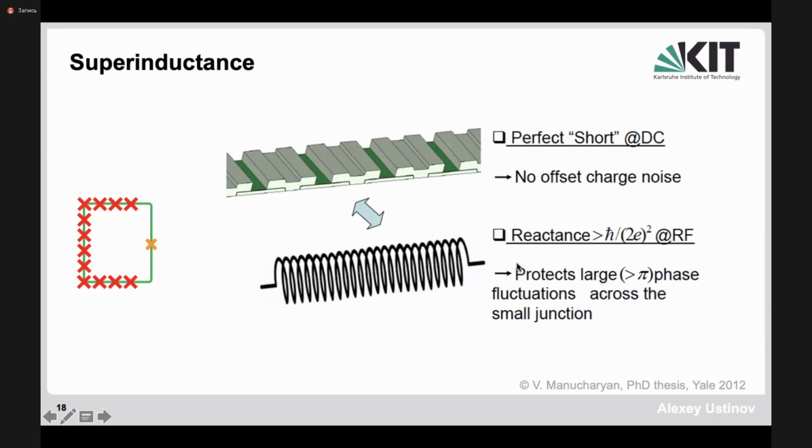As I said, the reason for using this inductance initially was thought to be the trick to avoid the low frequency charge noise due to the random charges which are moving on the substrate and fluctuating there at any temperature. They are present there due to contamination of the surface, due to charge traps and many other reasons. All the reasons for these charge traps are not really known. Many proposals have been made, but only few of them verified experimentally.